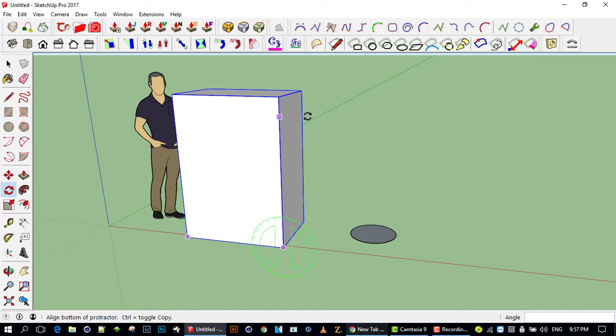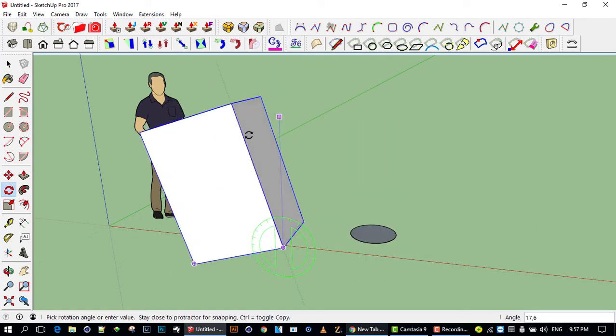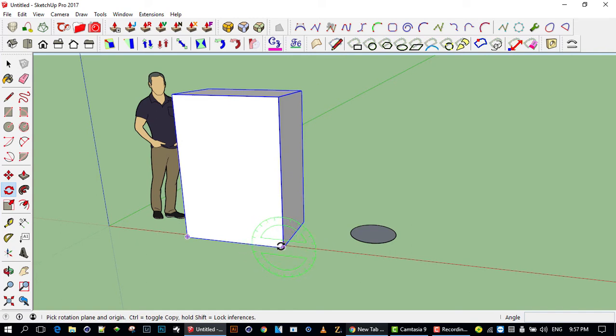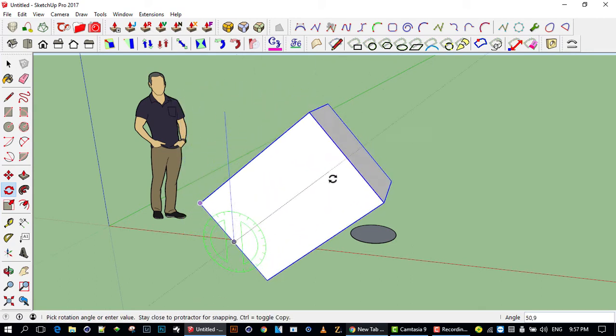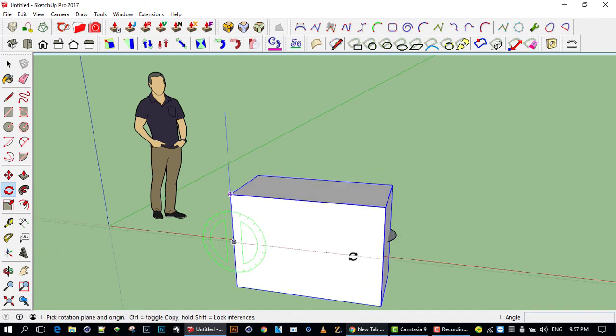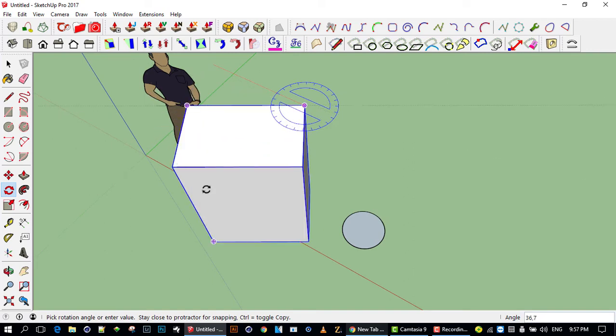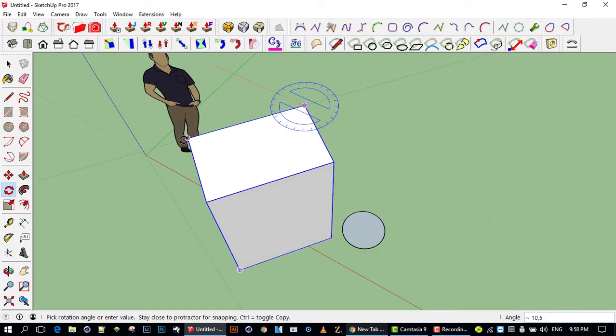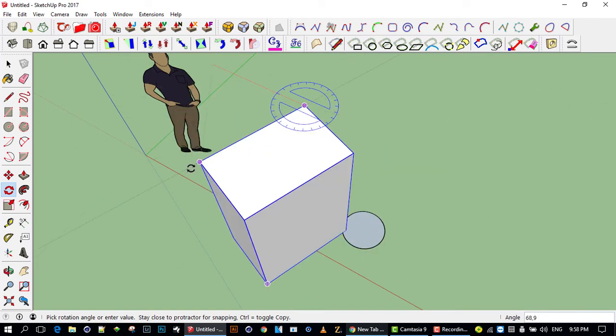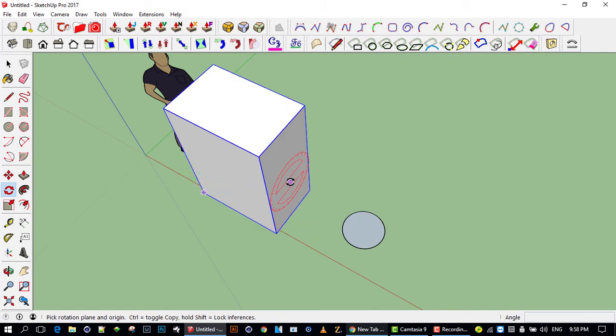You move along the axis and then you spin it around. So the whole idea is wherever you're selecting, in whichever plane you select, you click, and along that plane you choose the axis from which you're going to reference, and you click again, and then it will rotate from there. And this is very useful for things like doors. If you want to, in a model, you click here on the door and you click on section and you can open and close and rotate doors. It's a very thick door, this, but that's the way the rotate tool is used.